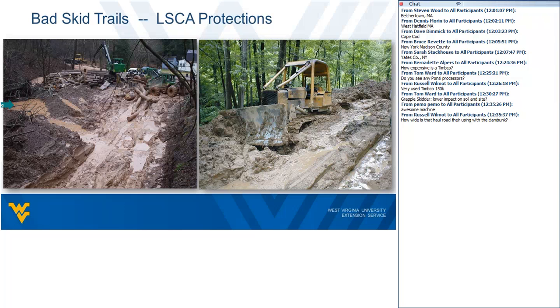If you're working on an operation and you see situations like this, it's best to get your operators to stop, and either come in there and fix what the problem is, or wait for the soil conditions to improve significantly before they continue operations.